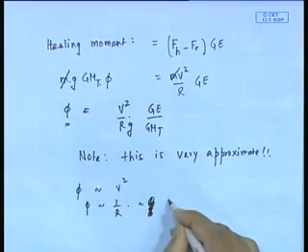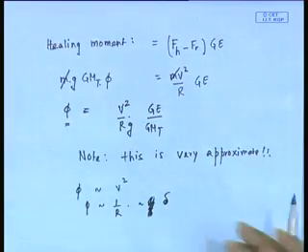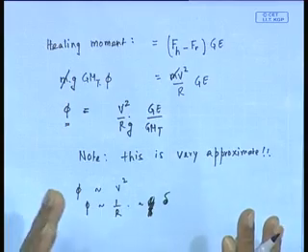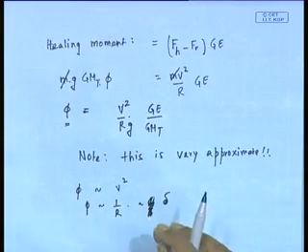Or yeah, no, so inversely proportional to delta, right, proportional to delta. So you understand that if I give a larger rudder angle, I have a tighter turn and a larger heel angle outward. If I go faster, my radius of turn is the same, but my heel angle is larger. And so if I am going very fast with a large heel angle and suddenly bring my rudder back to 0, I actually am looking at a dangerous situation.